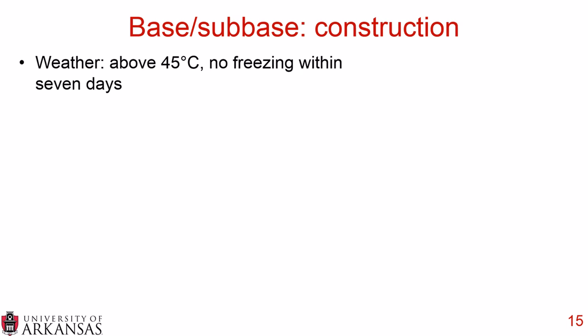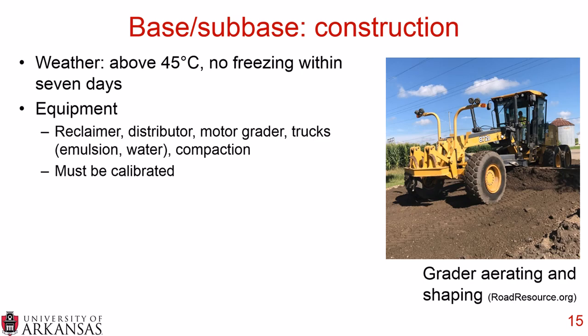When we're talking about the construction of base and sub-base stabilized materials, you want the weather to be above 45 degrees for asphalt emulsion, and you do not want any freezing within 7 days. You want that asphalt emulsion to fully break before freezing occurs.